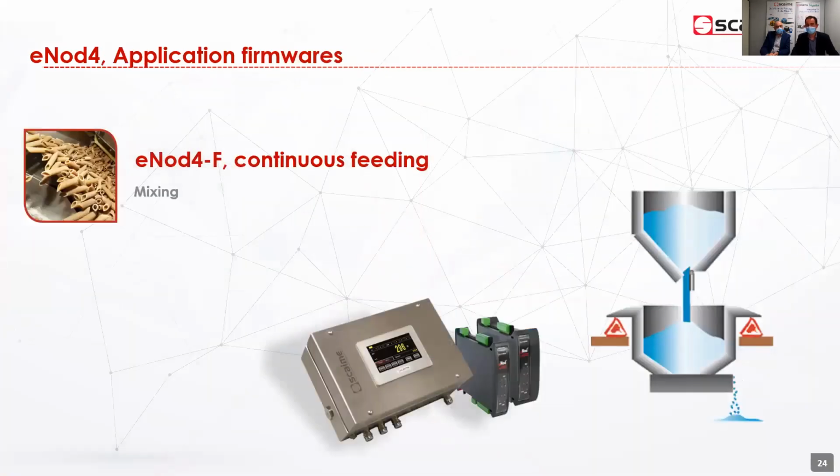So now the last firmware version available, which is in a way quite similar to the eNod4B. This is the eNod4F, F like feeding, so dedicated for continuous feeding application. Like the eNod4B, this firmware version is dedicated to material flow control and regulation. Also for the eNod4B, the main difference is the accuracy. Continuous feeding inside a tank by loss in weight feeding is more accurate than belt conveyors.